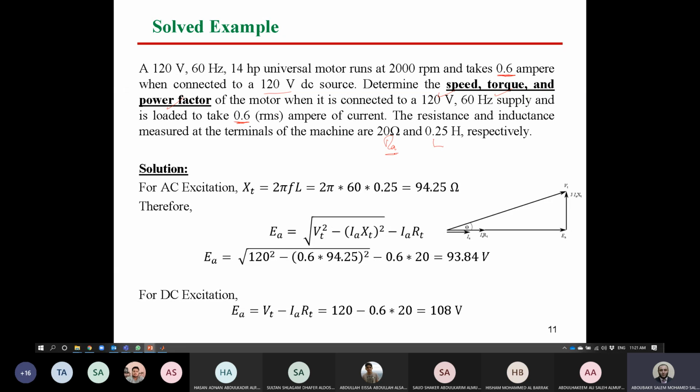So you have the value of resistance, but you don't have the reactance value. It's stated here the frequency is 60 Hz. So in order to get the value of XL, you can say 2π f multiplied by inductance. So simply substitute in the reactance relation to get the value of XL. If you do that, you will find that XL equals 2π f L, 2π multiplied by 60 multiplied by 0.25 Henry. And this, by the way, is a huge value. This inductance is a huge value. So you can find here the reactance is 94 ohms.